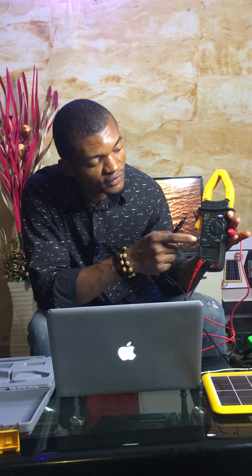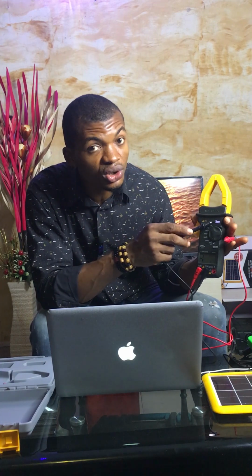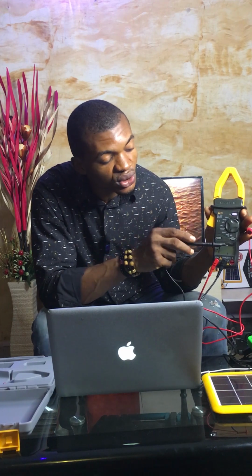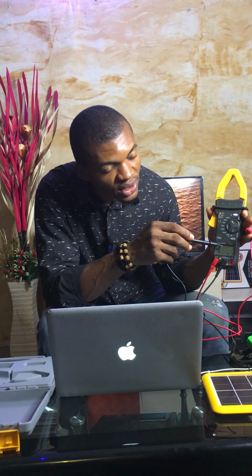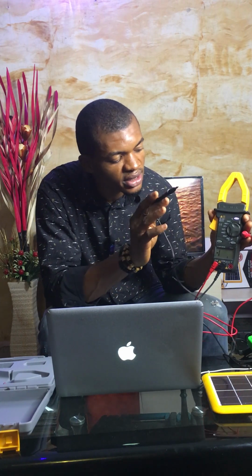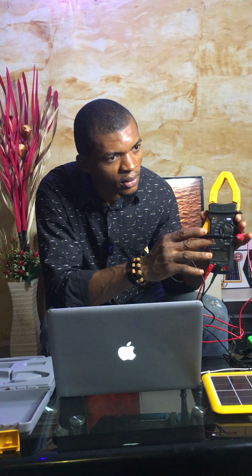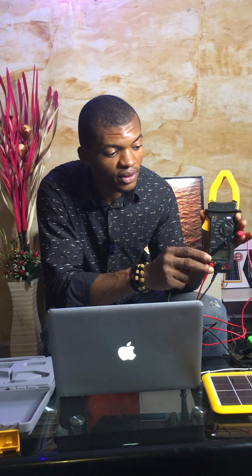Now it is in the position of the ohm. Sorry, I didn't tell you this on time. This is hold. This hold is used to show your measurement after you take it, and you don't want it to go out of the display until you take your record. All you need to do is press this hold and it will remain there. So now it is in ohms. I'm going to measure the continuity, listen and hear the sound. Can you hear it? This simply means that the probes are okay. There is no cut anywhere.